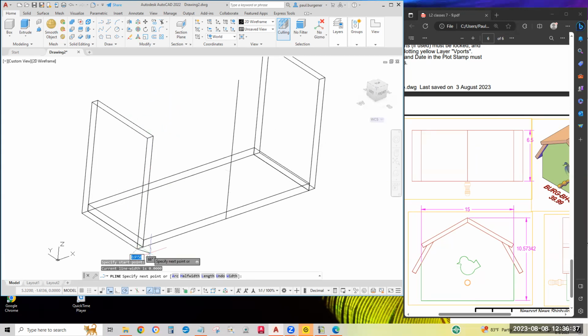On second thought, let's see. Why am I not getting the Z elevation? Tell you what, let's be on the safe side, let's set the UCS so that this edge is now the XY plane. Otherwise, I'll most likely be clicking in the background on the XY plane.